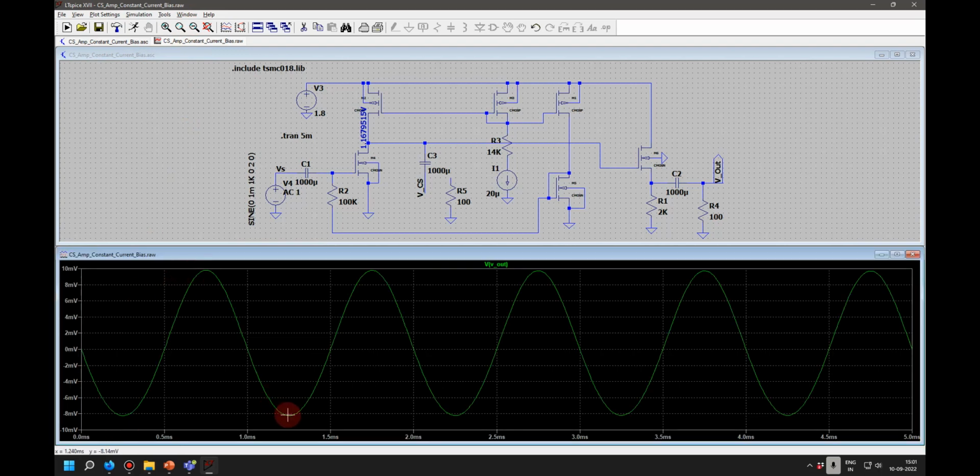10 millivolt to 10 millivolt, right? Obviously from here to here there will be some drop, since it is a unity gain stage. But earlier, if I connected this 100 ohms here, I was getting only microvolts. Now I am getting 10 millivolts.